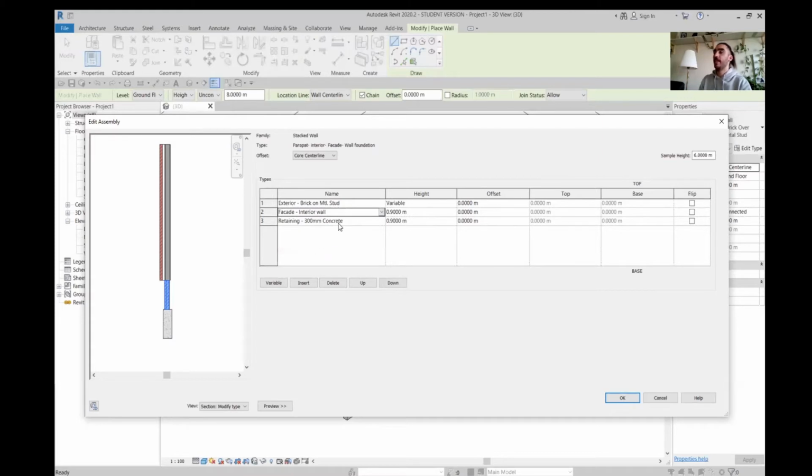And then getting much more up, the last section on top will be the same part, but this time with the parapet on. So again, just navigate among the wall and you will see the facade parapet wall. Click on that. And now what you have to do is to simply start to adjust the height. Let's say the wall foundation should be like 0.90. That's according to the design, that's what we need to have from the top of the foundation.